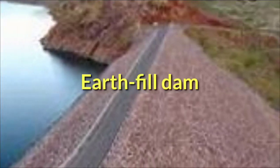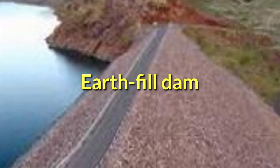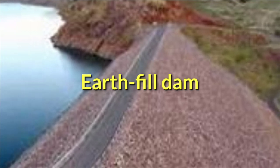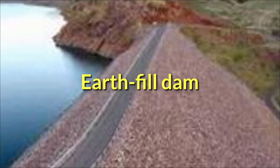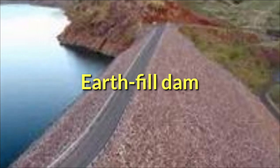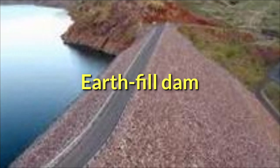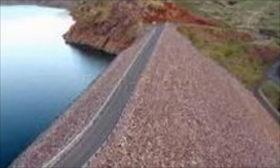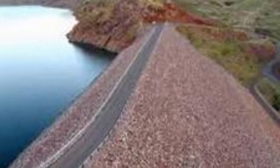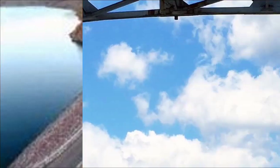Next is the earth fill dams. Earth fill dams, also called earthen dams, rolled dams, rolled earth dams, or simply earth dams, are constructed as simple embankments of well compacted earth. A homogeneous rolled earth dam is entirely constructed of one type of material but may contain a drain layer to collect seep water, and can be effective in regions where the cost of producing or bringing concrete is prohibitive.